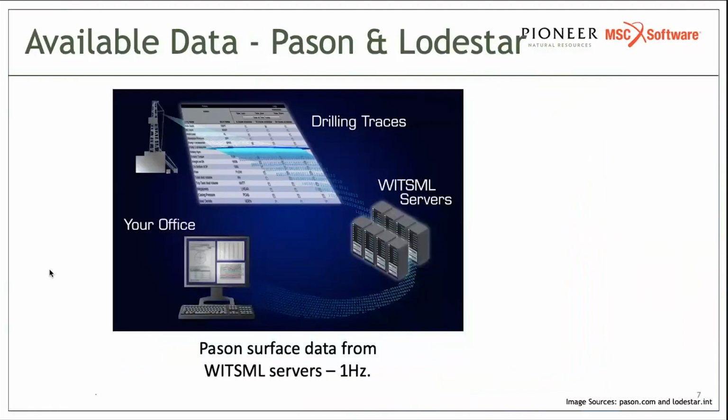I worked with 2 different datasets from Pioneer. First, drilling parameters were obtained from Payzone. Payzone is a company who has various sensors in our drilling rigs and can send us all the surface data in real time using WITSML servers. It is available at a frequency of 1 Hz, meaning that we have 1 data point every second.